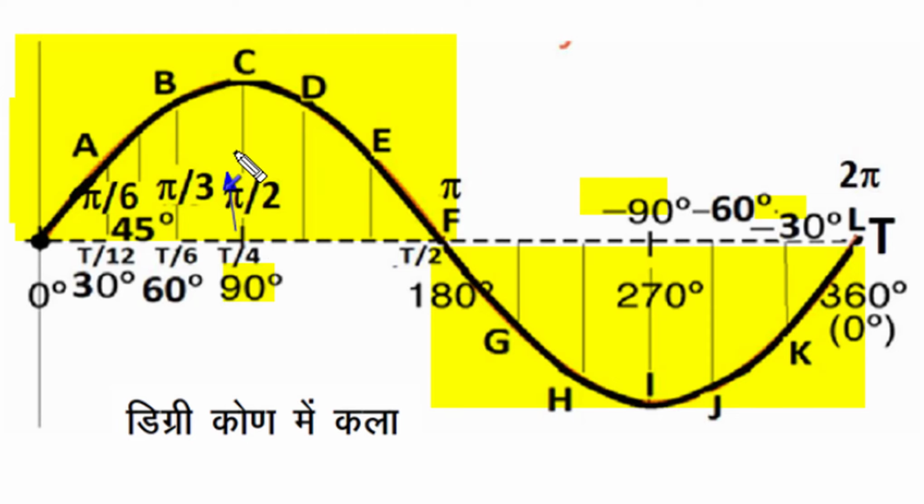That means from the peak to both sides, an identical phase difference will fetch identical values. From the 90 degree phase condition, if we reduce 30 degrees of phase, at 60 degrees the instantaneous magnitude, and at 120 degrees the instantaneous magnitude, is the same. Similarly, at the 30 degree phase condition and at the 150 degree phase condition, the instantaneous magnitude is the same, because this sine wave has a quarter wave symmetry across this 90 degree phase instant, or positive peak.